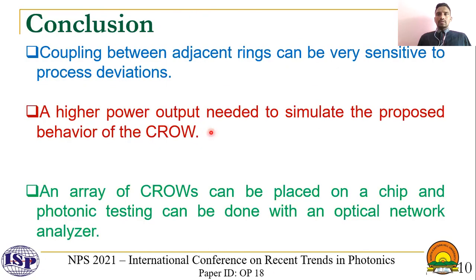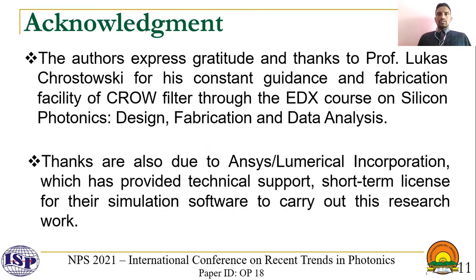So I will conclude my discussion. The coupling between the adjacent rings can be very sensitive to process deviations. A high power output may be needed to simulate the proposed behavior of the CROW. An array of CROWs can be placed on the chip, and photonic testing can be done with an optical network analyzer. So now finally, I will acknowledge the authors.